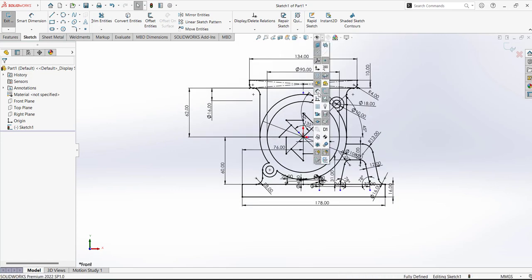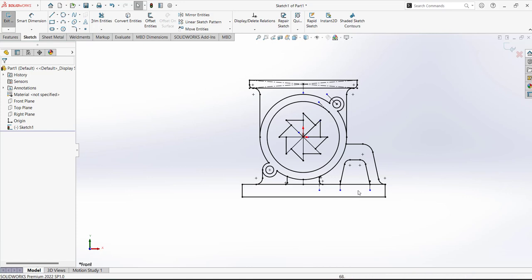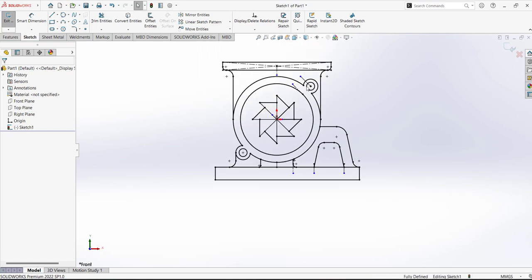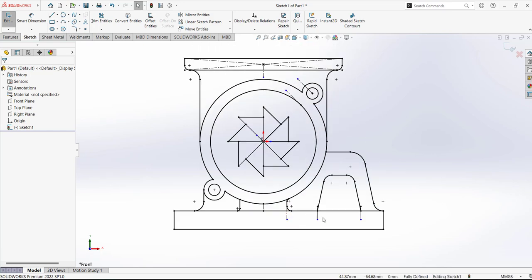We'll again hide the dimensions here. Now you can see this profile is completed. We can also see that we have made this profile completely fully defined and constrained. It doesn't matter if the construction lines are underdefined here. We just need to define all the solid lines so as to position each and every line and entities. So this was the exercise showing maximum commands of sketches here.